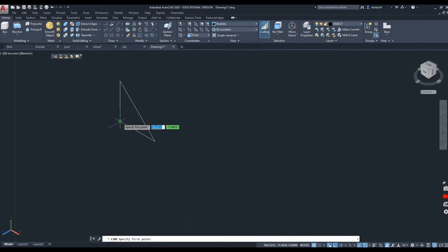Okay, now that little triangle actually goes down into the part. So what I'm going to do is draw a line from here, and I'm going to go down one more. Okay, and I'm just going to go out to here. Now I'm going to extend this line till it meets. Okay, now it's probably overkill, a little too much, but that won't hurt anything. So I'm going to trim this guy away, delete that guy, might have 2 of them. I will make this a region.